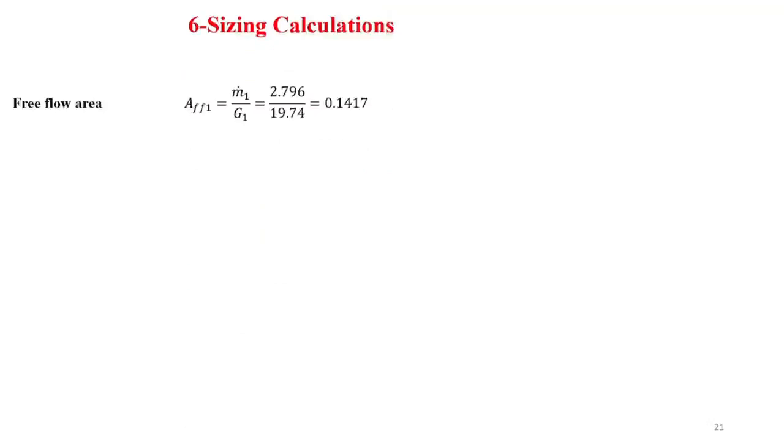Now you calculate the free flow area. By definition G is the mass flow rate divided by the free flow area, so you can find the free flow area. We divide the flow rate of side 1 by the G1 that we estimated. This is the free flow area, and it is going to be 0.1417.